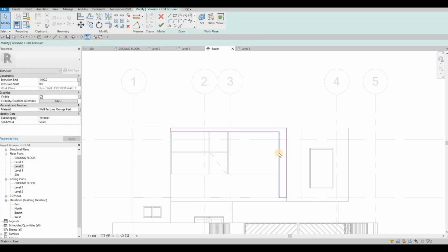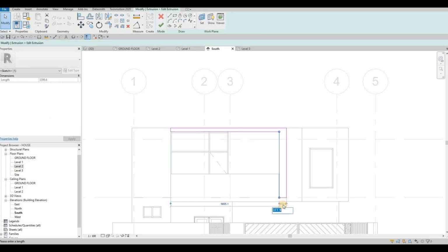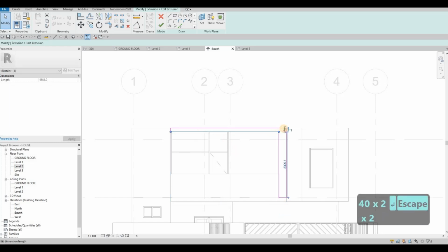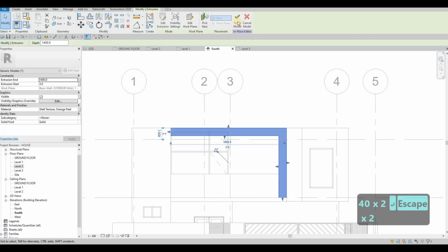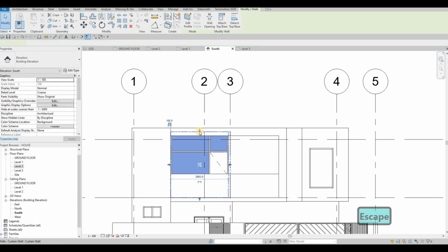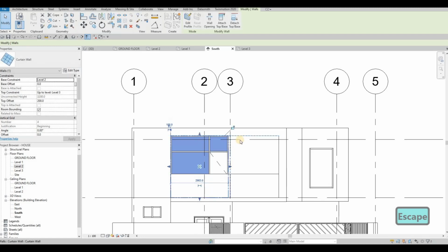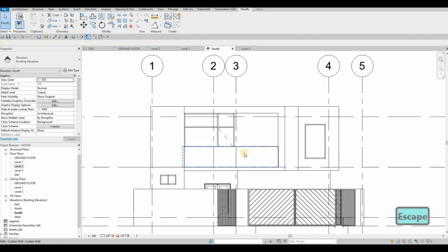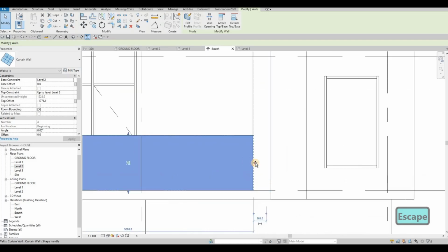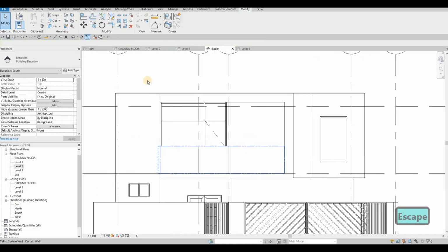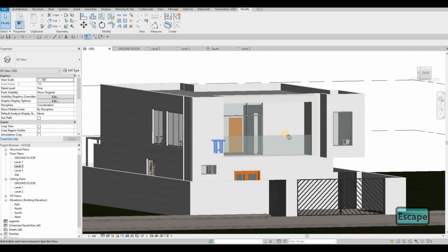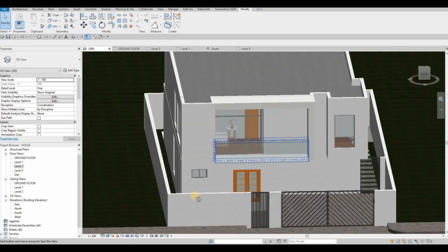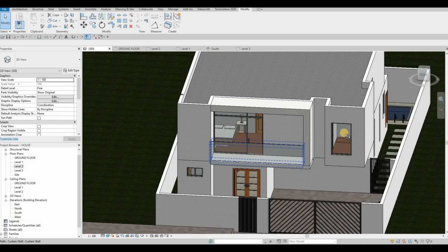So I'm gonna edit extrusion. Let's make it 400 to make it thick enough. Then 400 here. Click finish, and then finish. And then here we could just pull it down a little bit like that. So everything still is looking good. And then here we just need to move it like that right there. I think that's good enough. Good enough size.